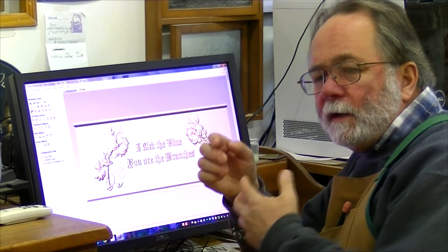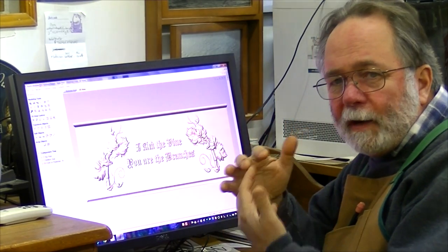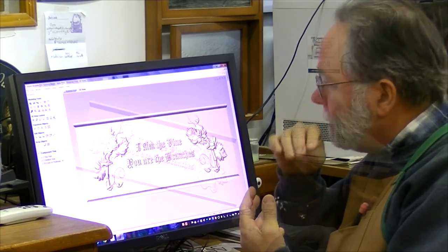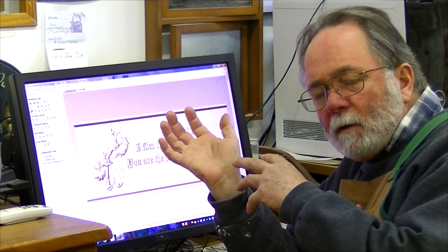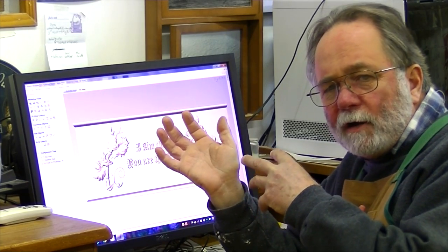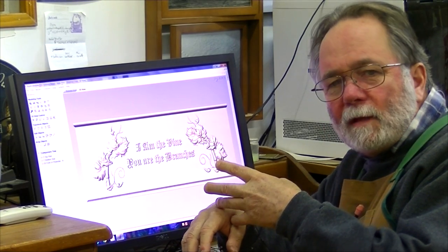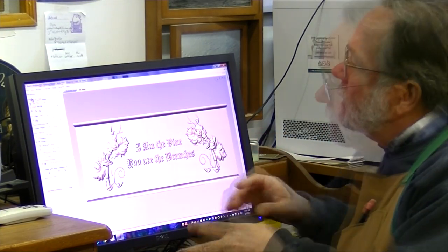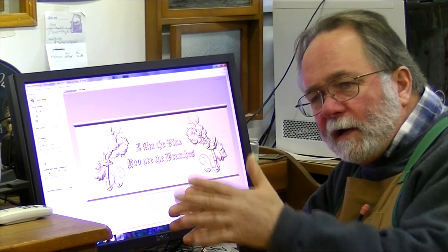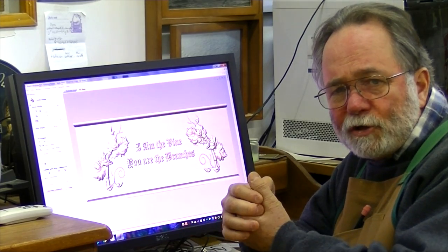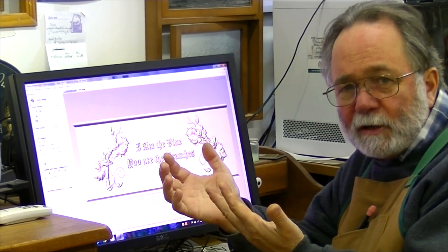Now this lettering is also cut in relief. In other words, the letters are proud of the final surface. The way I did that was to make the vectors of the letters using this Old English script, and then create shape to make letters with a slightly angled side and a nice rounded upper edge. And so each of these is in fact a little three-dimensional model.